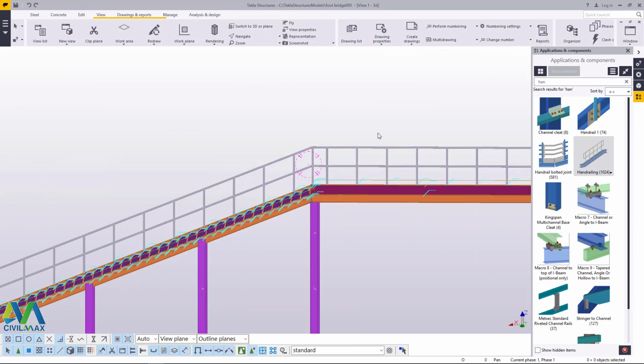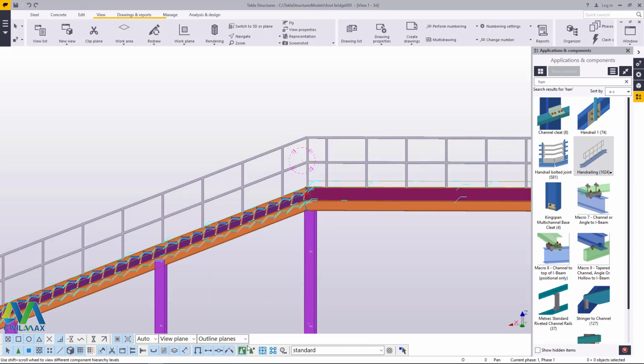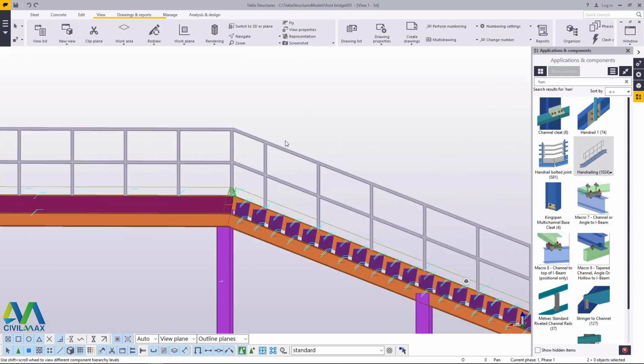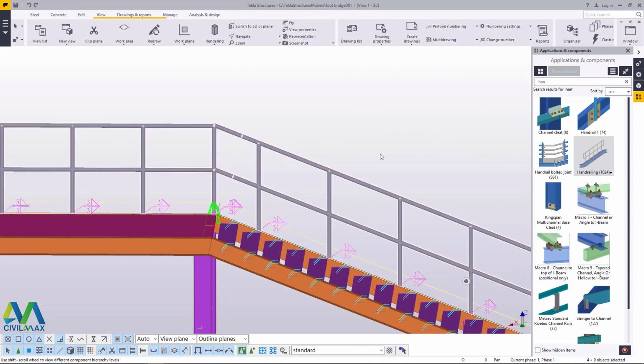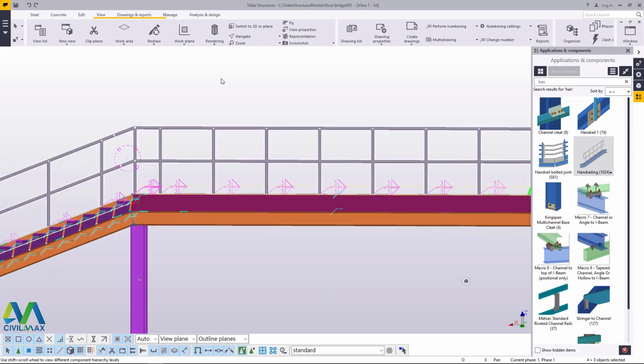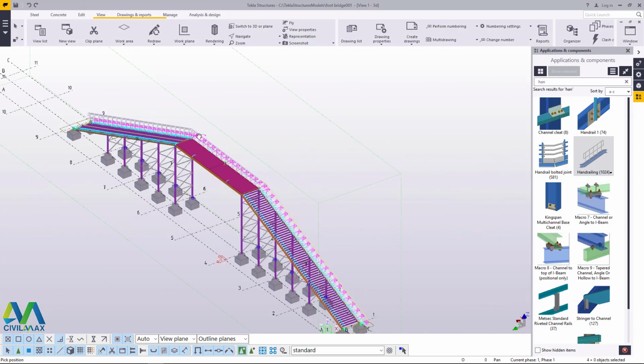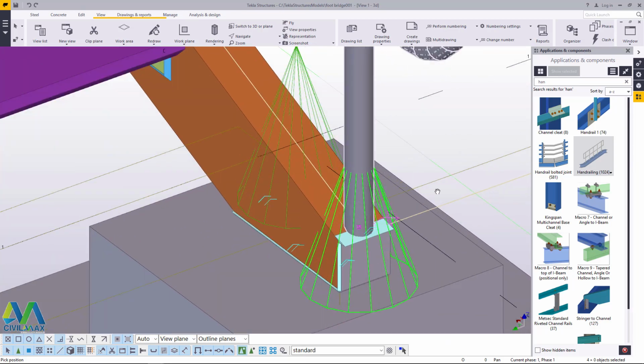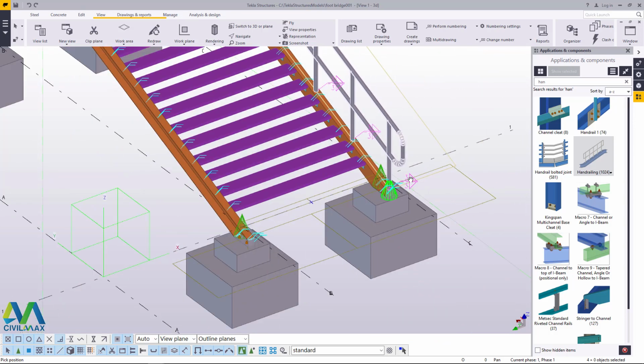To copy all these handrails, this end will bring back the assembly. We will activate the assembly button here by clicking on that end and selecting it. Then press Ctrl and come to this end and select. Make sure everything has been selected prior to copying at this end, because otherwise it will make you do this job twice, which is a waste of time and is not really good. As they say, time is money.